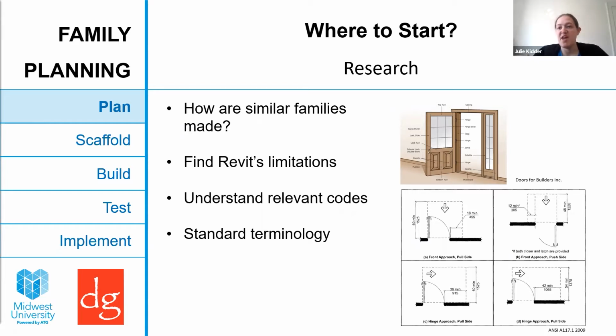Figure out what Revit's limitations are. Revit is by no means a perfect program, and there are things that Revit doesn't do well, and that means you need workarounds, or certain ideas have to be discarded until a point when they might work. One of my pet peeves is that I can't have a child family tell a parent family anything about itself, which means I have to look at how to pass that information in a different way, or how to not need that information.